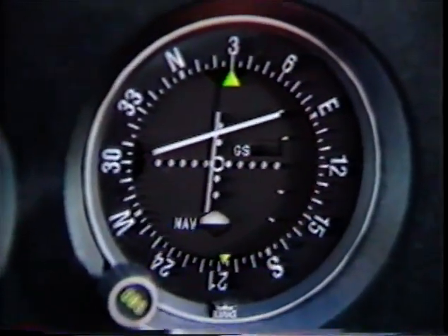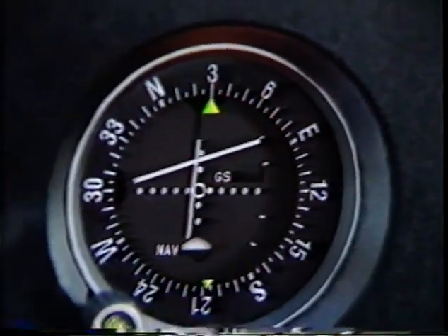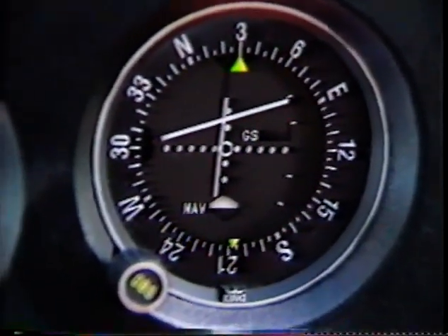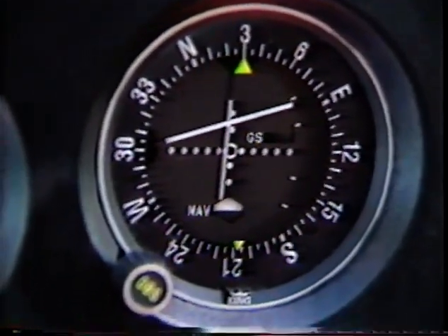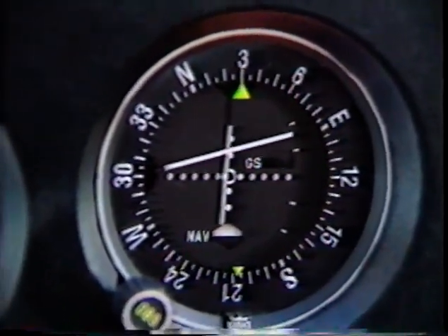As you descend on the glide slope, the wind may shift and the reference heading may change. This will be apparent as a correction towards the needle stops, but it does not bring it in. The new heading is now the reference heading, and further correction should be made in relation to it.